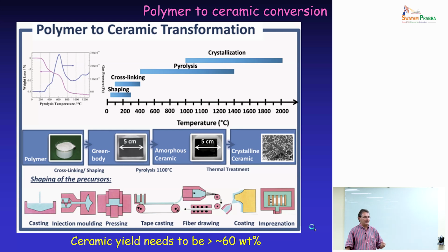The bad preceramic polymers, like commercially available UV curable siloxane, have been developed for conformal coating of electronics, for instance. They have linear chains, and the weight loss is very high because they have not been designed to withstand high temperatures. So in that case, the ceramic yield is as low as 5%. All the rest is eliminated.